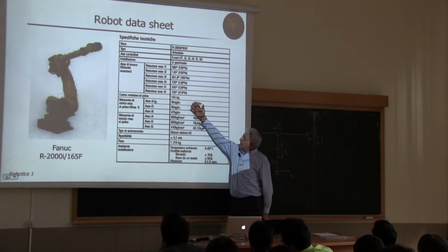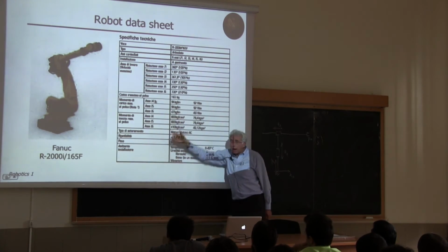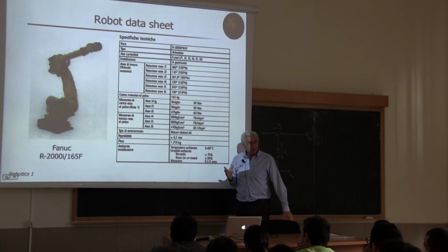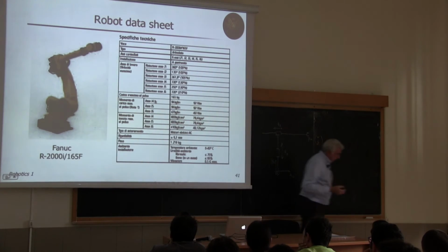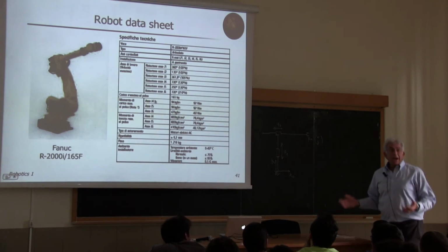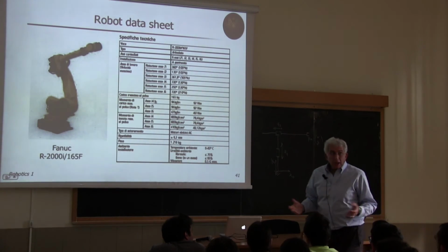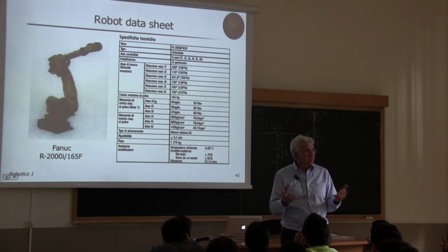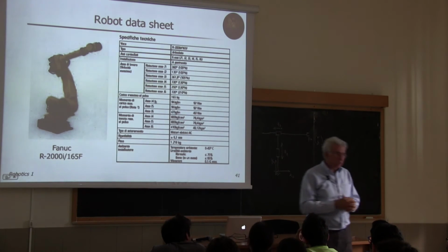This is very critical, and this is why the last generation of robots tends to use different materials and different design to make things lighter, although not flexible. If you're using, of course, aluminium, you're saving. If you're using carbon fiber, you're saving a lot, and you have a very stiff structure, but they cost a lot. So it's a trade-off again of cost and performance.